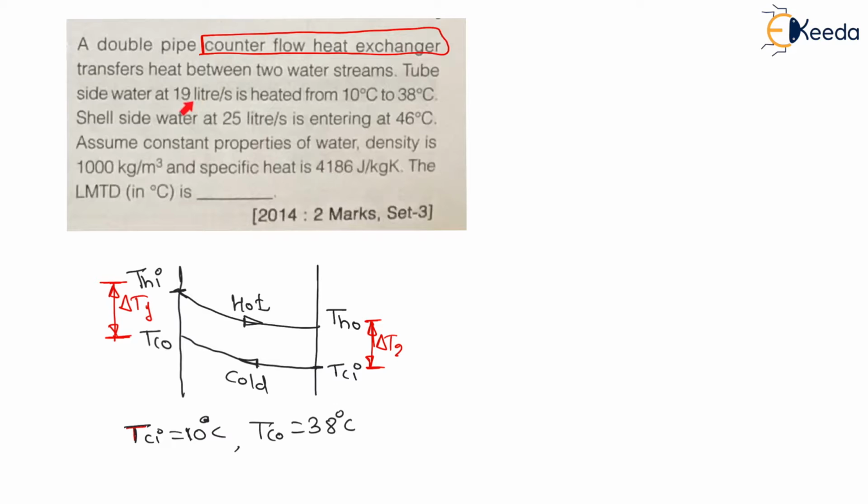And here volume flow rate is given and it is nothing but mass flow rate, because my dear students, 1 liter water I am saying, not for other fluids, 1 liter water is always equal to 1 kg water. This is valid only for water if density is 1000, right? For rest fluids it is not valid. Now let us see, here density of water is given 1000.